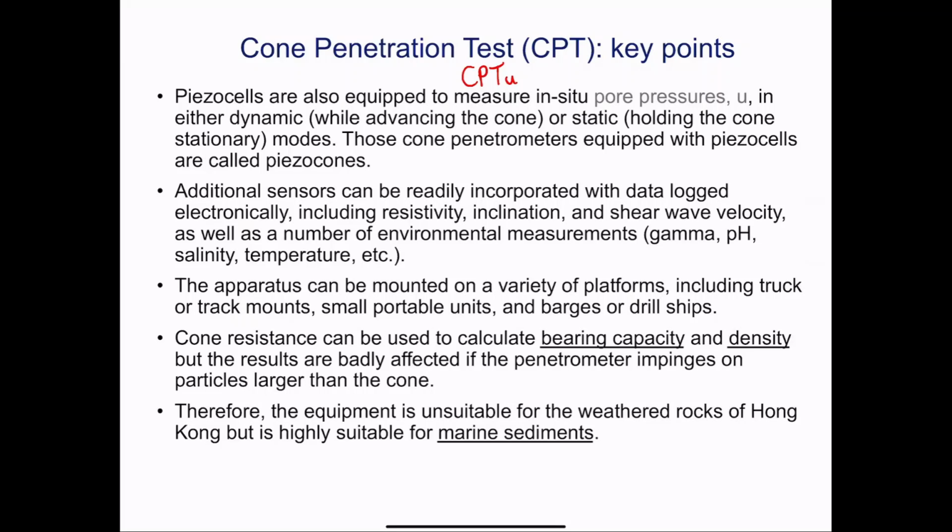The core limitation of CPT is perhaps if you run into very granular material, corestones, boulders, then you're not going to be able to push it through. Then you have to extract, find another location, and penetrate further. This CPT test, as we've discussed quite a bit, is quite suitable for marine deposits, for land reclamation, but you won't see this being used for CDG slopes or ground material, or weathered rocks of Hong Kong.